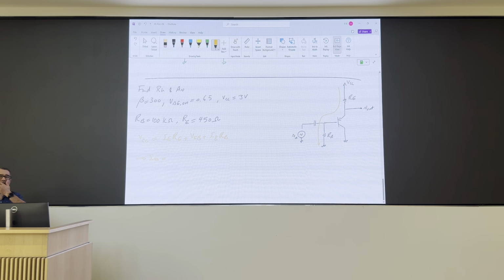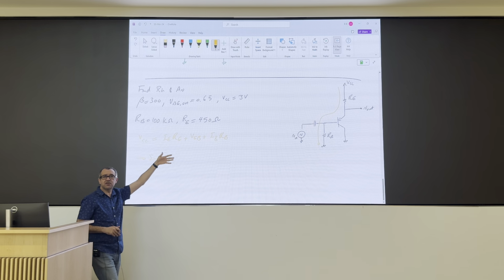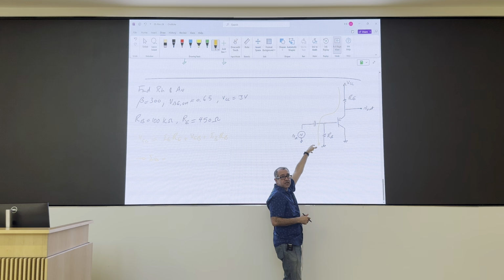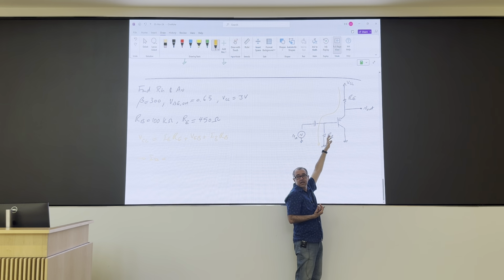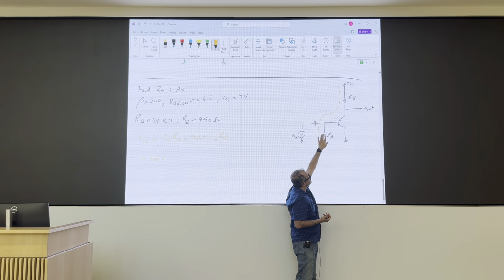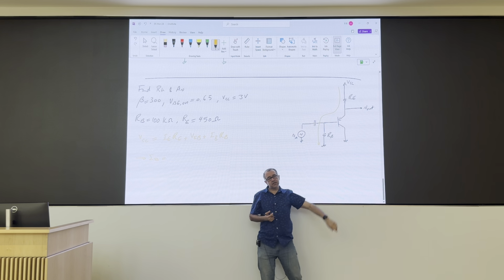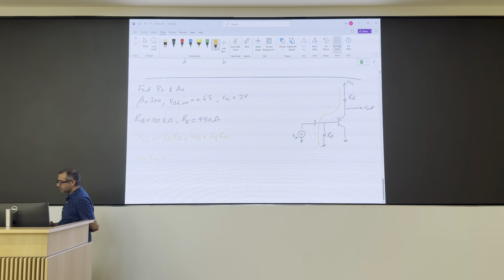This is a biasing technique that we said is okay to use if you're making 1 or 2 circuits, but in general, this is not super stable, right? It depends on beta. Otherwise, you want to use H biasing, that's your go-to method. So I put 1 resistor at the top as well, and form an H. Anyway, this is easy enough.